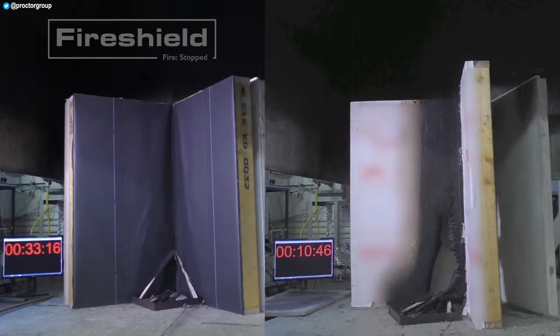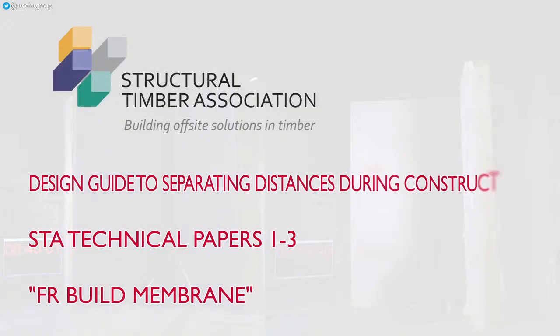Fire Shield is the first fire-resistant vapor-permeable membrane approved for inclusion in the Structural Timber Association tested product listing for fire robustness during construction. As part of an appropriately tested construction, Fire Shield can be used as part of a system to limit the spread of fire, which can allow for reduced spacing to adjacent properties. This must, however, be done in accordance with the Structural Timber Association's procedures and test methods.